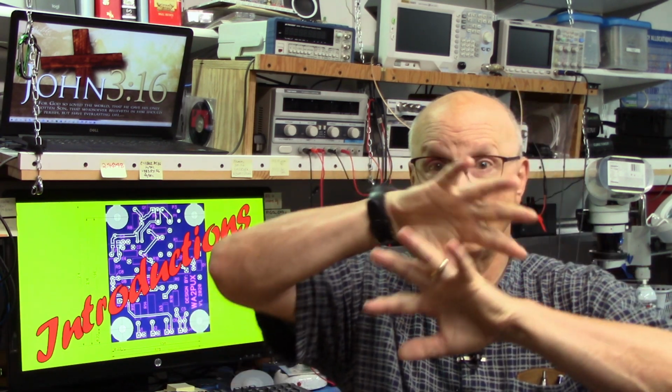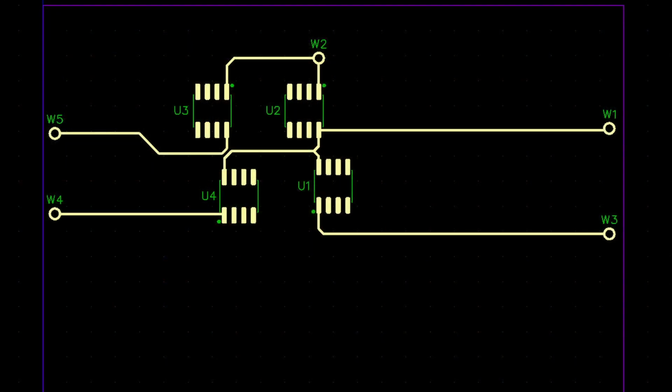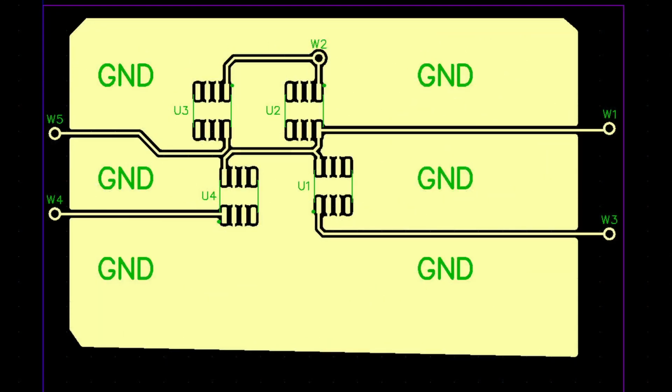Now, the last thing I have to address regarding copper pours are the areas of disconnection between parts of the plane due to traces. So you have this board with various traces running all over the place and signals and all this kind of stuff, and then you place your copper pour over the whole layer for a ground plane.